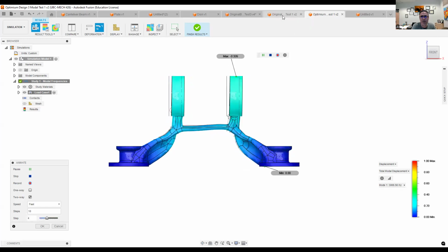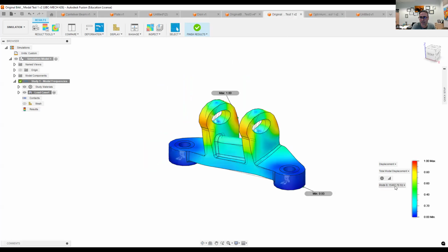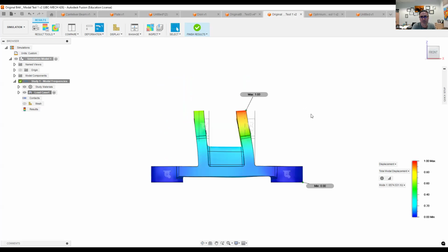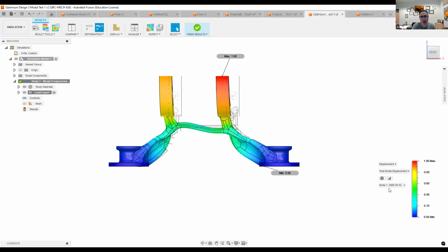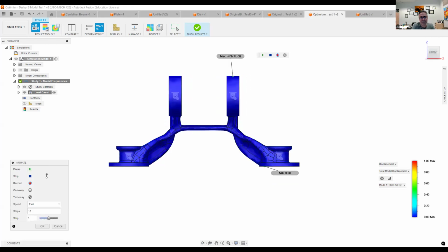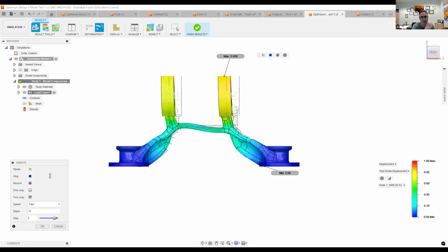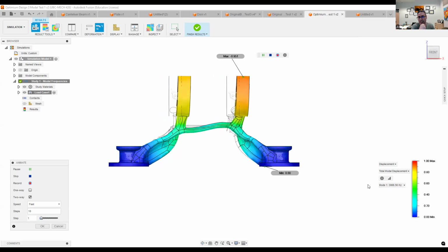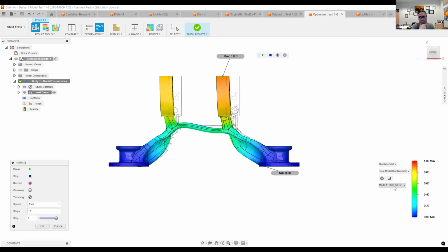Let's go back and take a quick look at the first frequency of that one. It's 6500. It seems the mode shapes are very close, but you saw the frequency becomes almost half. It's an indication that it's not just the stiffness, because we reduced the mass, the ratio of stiffness to mass dropped, and the square root of that dropped by half because the natural frequency is about half.